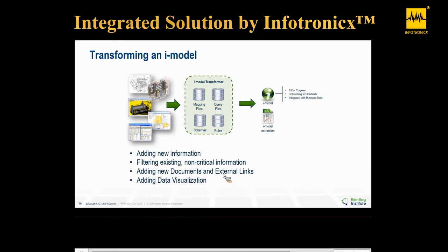Bentley developed the iModel transformer as a way to adapt this information for downstream requirements. With the iModel transformer, you can tailor information produced by applications to filter out data that's not required, or to add information from sources like spreadsheets, schedules, or maybe even other iModels. This allows us to combine information generated by different applications and work with it in a uniform way.